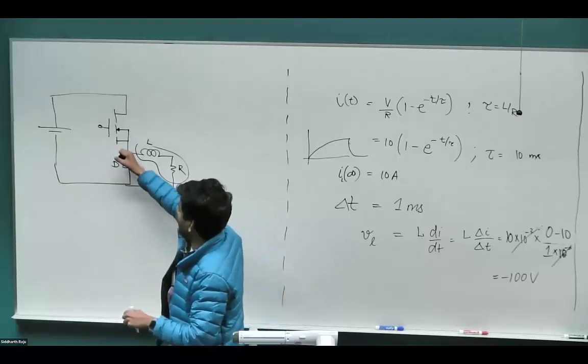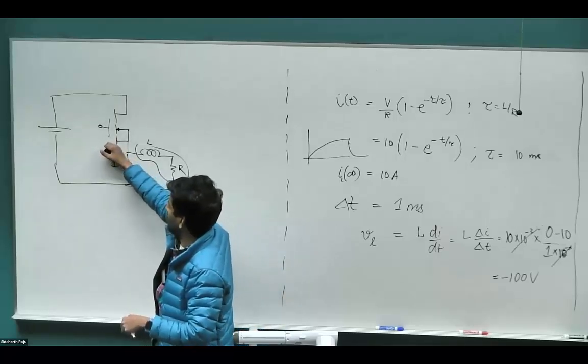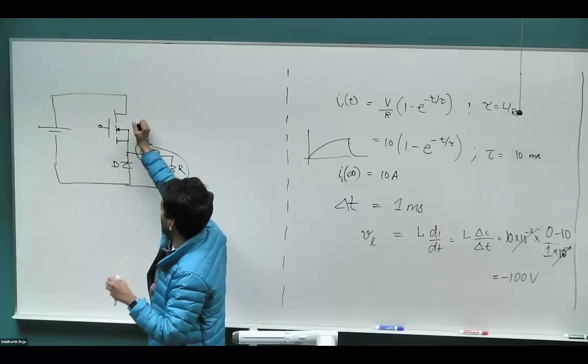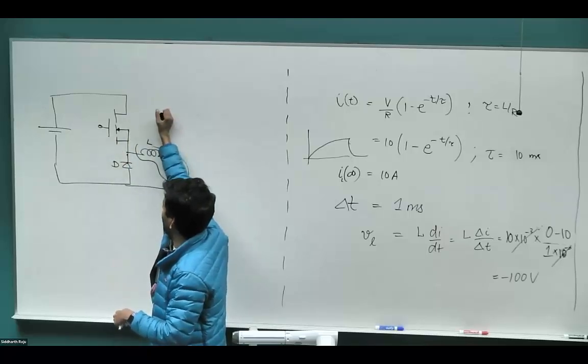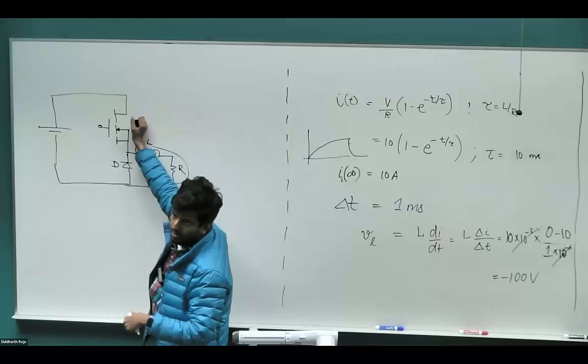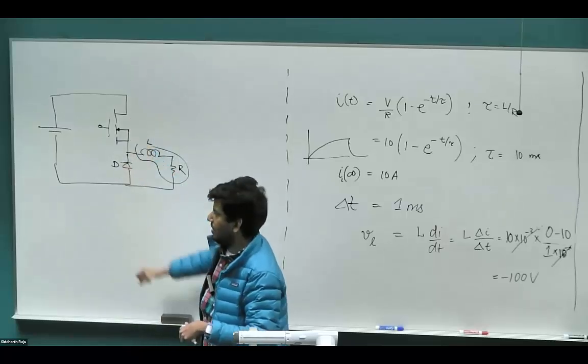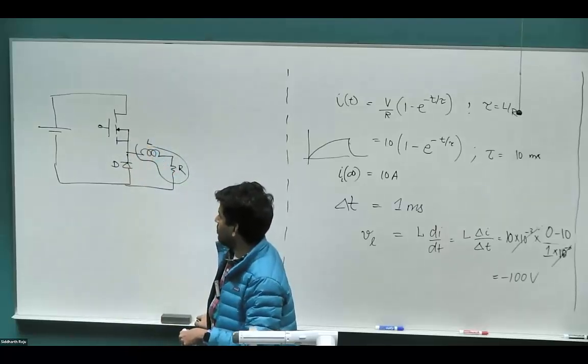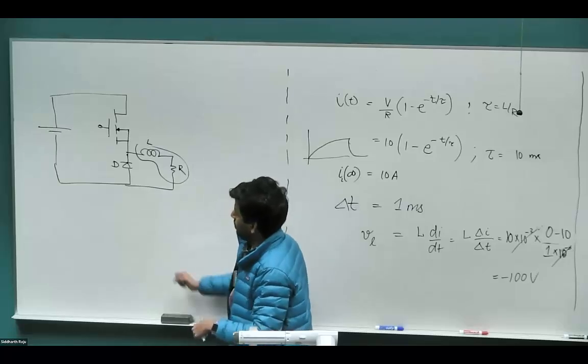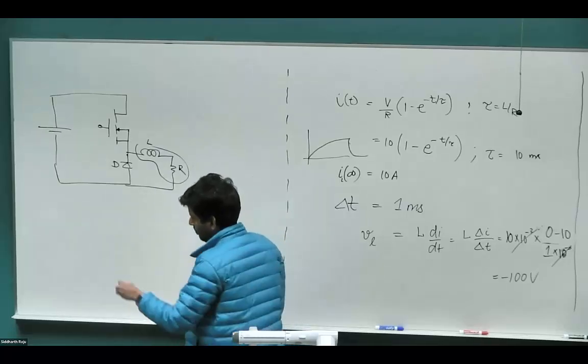So even if there is no way you can physically create a MOSFET without a body diode, but by some theoretical miracle, let's say you're able to get away without the body diode, you would still want the body diode to be there because it's part of the operational requirement of converters, as we'll see in a minute. Right? So this is the structure, and the way this MOSFET works